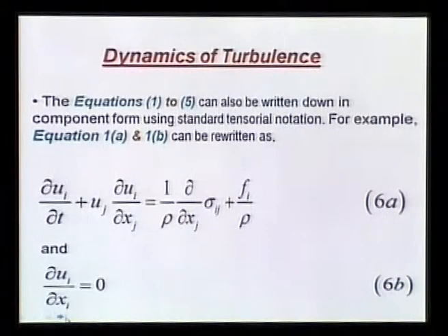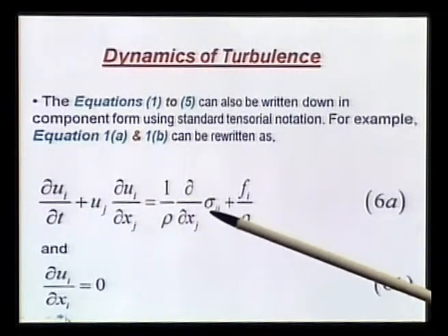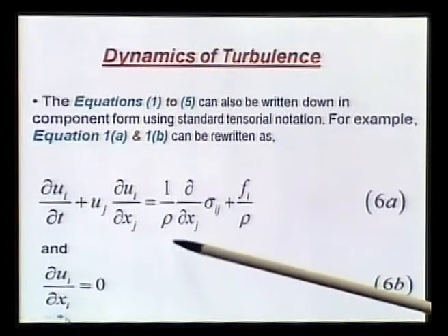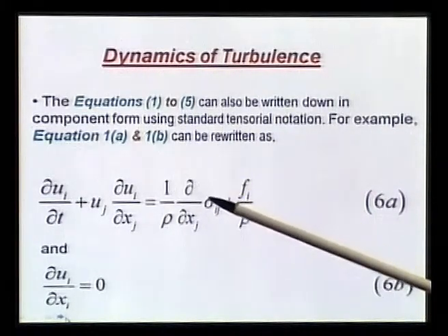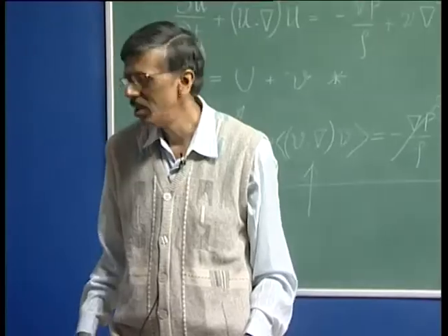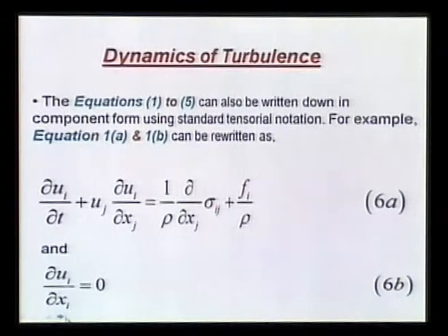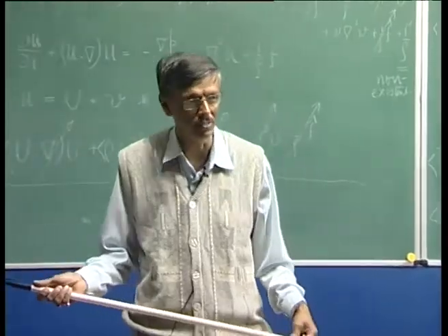So, you can very clearly see the local acceleration, the convective acceleration, and this is a stress term. If you recall, before the Navier-Stokes equation was written, this equation was in vogue, and it is attributed to Cauchy. So, this is also called the Cauchy equation.